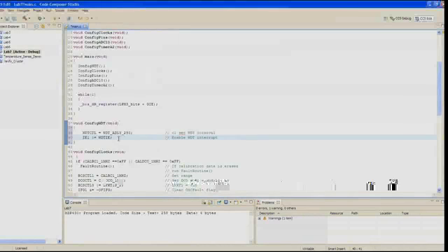The selection of intervals for the WDT Plus is a bit limited, but the WDT ADLY 250 gives us a sub-second delay running on the VLO. Those bits set the following. They set the watchdog timer password, they select the interval timer mode, they clear the count value, and they set up the watchdog timer clock source select to the one that we're interested in.